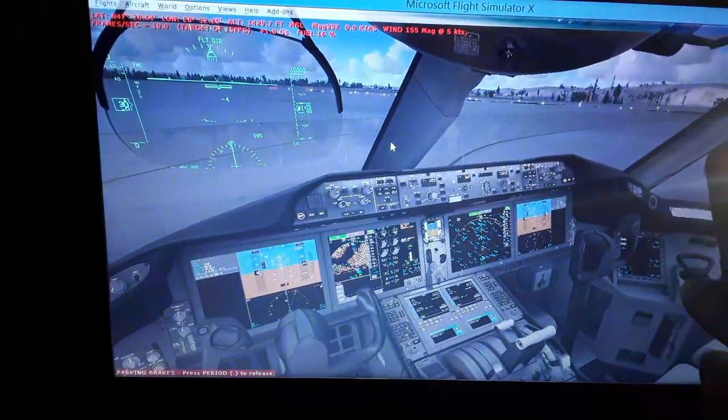We have the airports displayed in the terrain map with a four-letter ICAO name in blue letters, and also we can see the runways we're going to use for takeoff and landing, and the taxiways of each airport, the runway length and the direction, so we can align with the magnetic compass or geographic. We also have the navigation aids such as ADFs and VORs. We have the nav aids and also the waypoints, which are horizontal and vertical navigation fixes and altitude and speed constraints that the aircraft is going to have to fly through when we're flying.